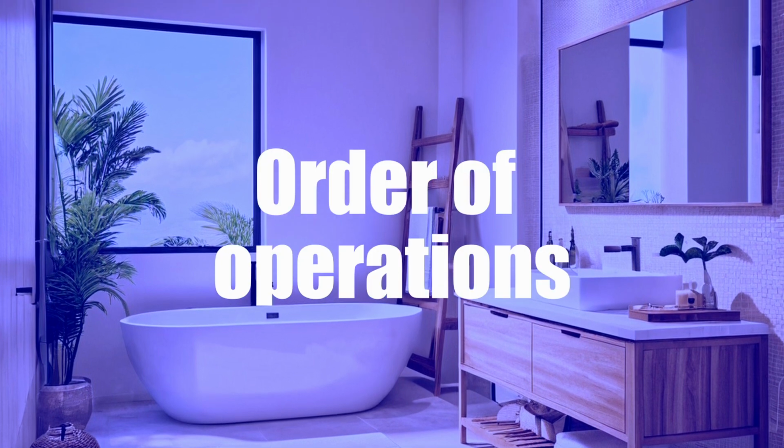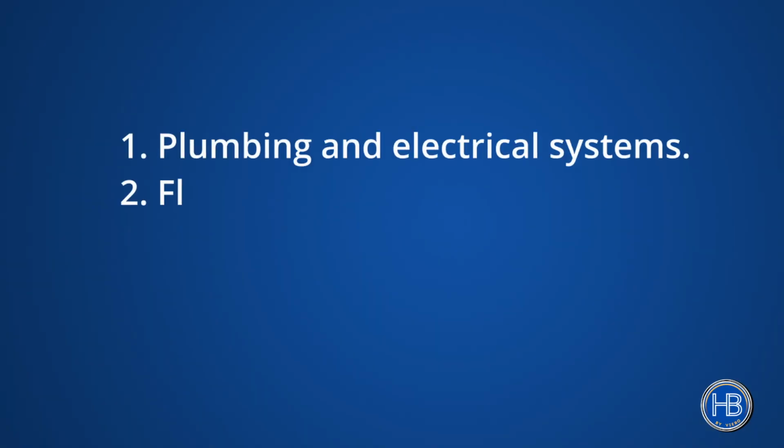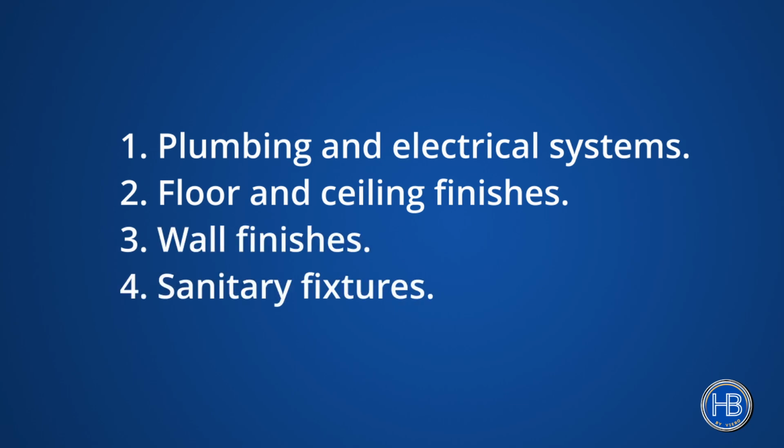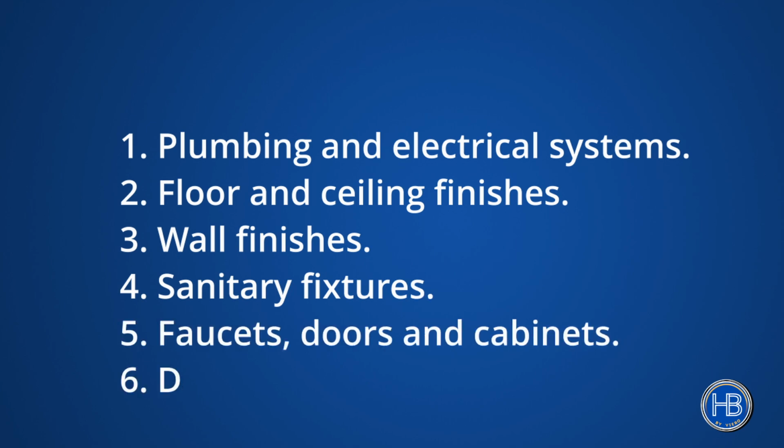Order of operations. Stick to this order for bathrooms to avoid damaging finished surfaces. 1. Plumbing and electrical installations. 2. Floor and ceilings finishes. 3. Wall finishes. 4. Sanitary fixtures, toilet, shower plate, etc. 5. Faucets, doors and cabinets. 6. Decor. Now final checks.